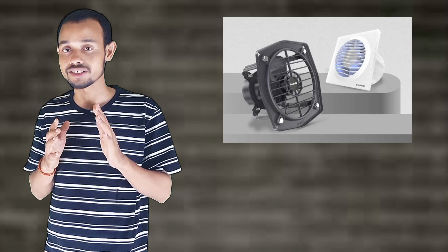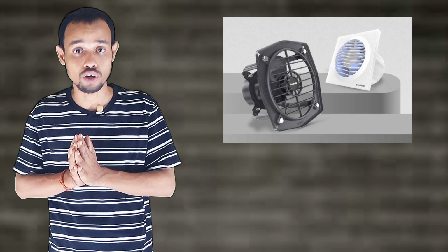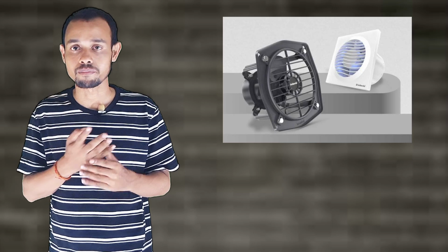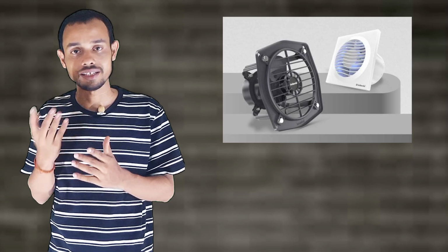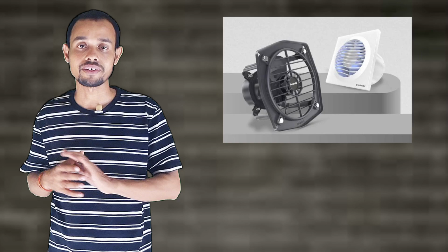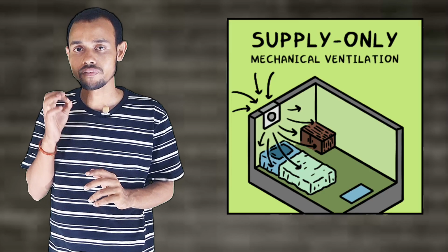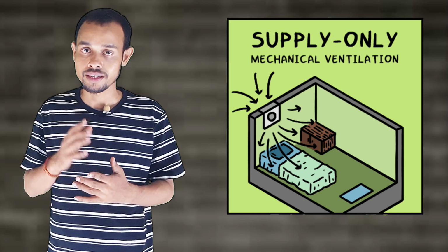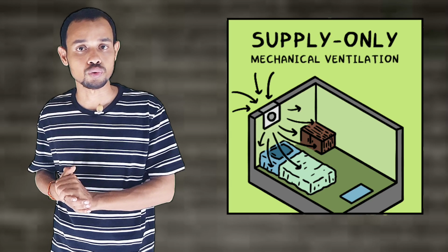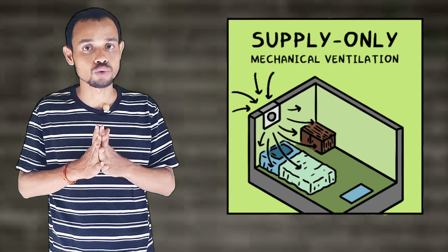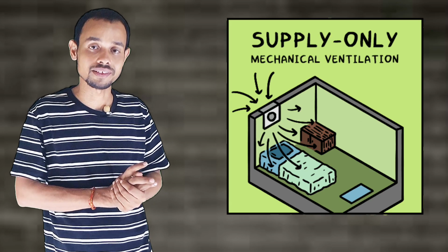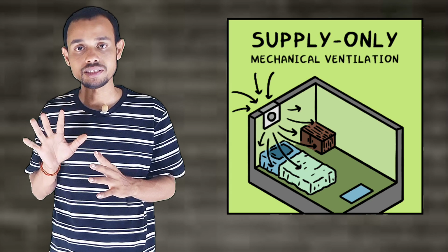Exhaust ventilation is designed to remove the dirty air, only used in the kitchens, bathrooms, parkings or the chemical areas. And fourth is the supply ventilation. What is supply ventilation? Supply ventilation brings only the fresh air in. Okay, it creates positive pressure so that the dust and the pollutants do not come into the offices and the rooms.